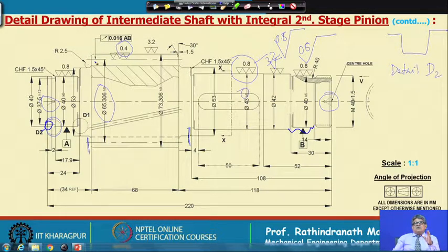For this gearbox that we have designed, we need not go for grinding, a good hobbing will do. Perhaps we can put a little more, a 0.6, 0.7 micron surface finish will do. And here, as you see, we have mentioned the corner radius. Another important dimension, if you look into that,